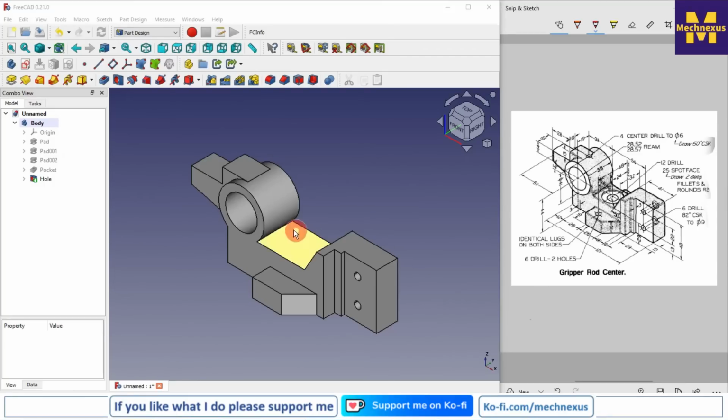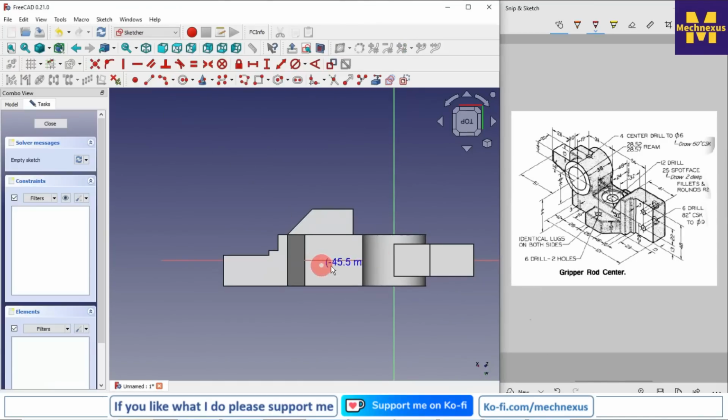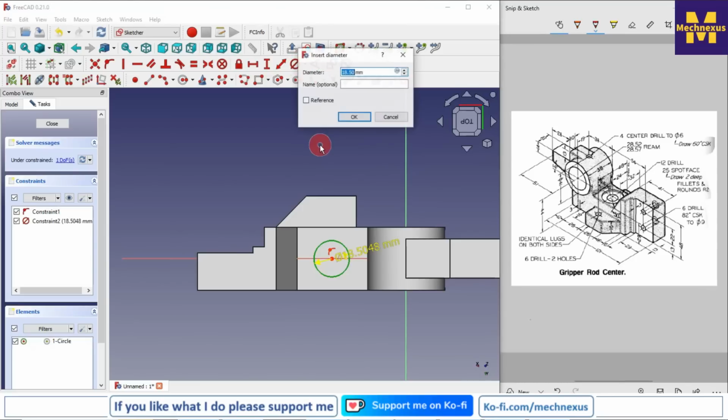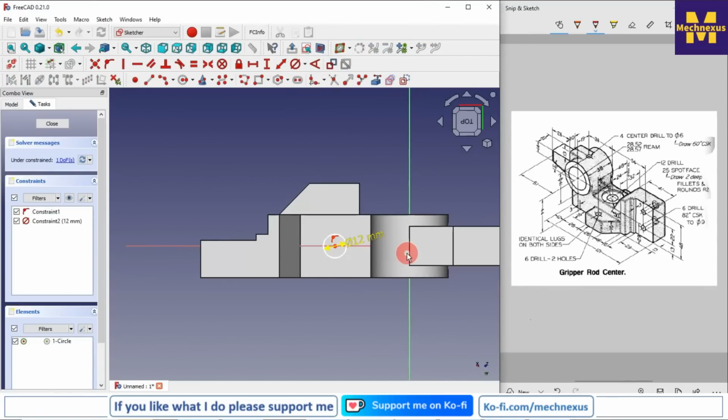Now the next feature we will create is a counterbore hole, which is given here: 12 drill, 25 spot face, 2 mm deep. So we will select this face and create a sketch, and now we will click on the circle and create a diameter, and here is a 12 mm drill, so I will select the circle and give the diameter of 12 mm, and from the center it is 38, so we will project this edge because it is at origin.